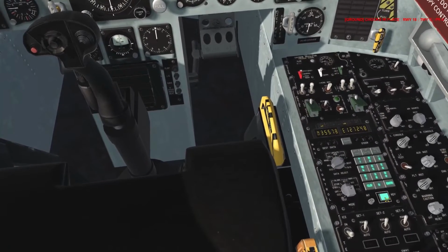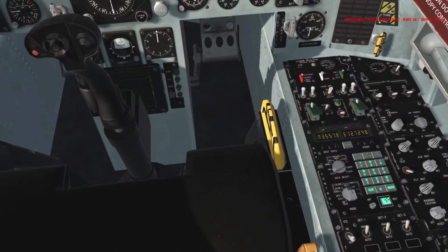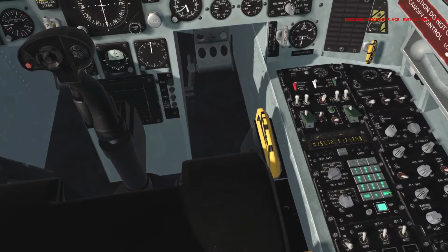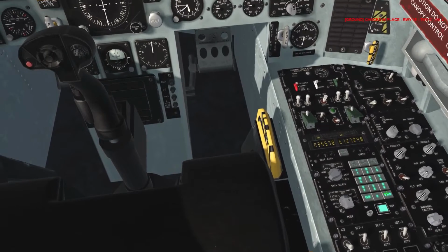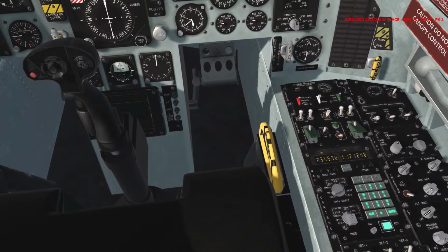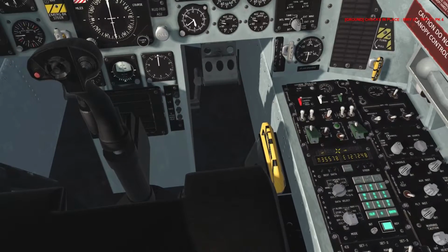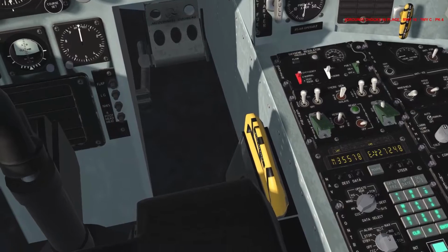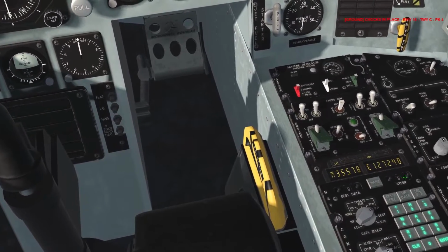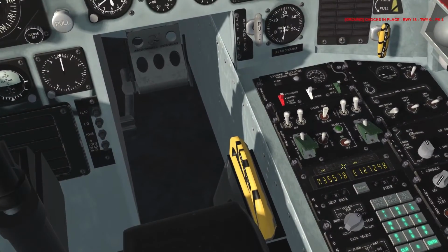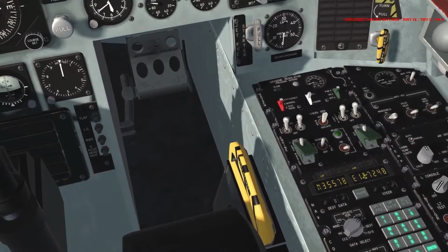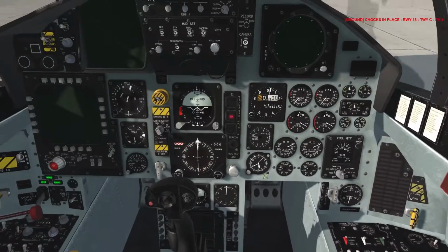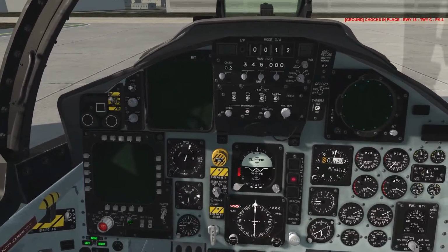Numpad, press ready. Verify NCI lights on. Numpad, press enter, and this is going to start the alignment process. So after 60 seconds, we'll have a course align, and the align light just here will be solid. After 120 seconds, we'll have a partial alignment, and that will flash at 1 Hertz. After 240 seconds, we'll have a full align, and that'll flash at 4 Hertz. So now we can continue with the rest of the setup. So the MPCD can come on.